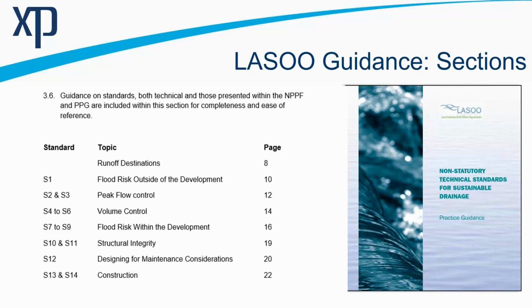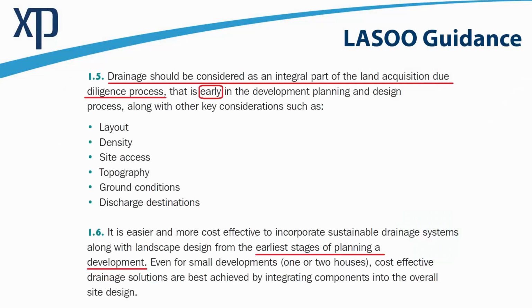With regard to the drainage, the key advice here is that you need to consider this at a really early stage. And when they say early, they mean it's an integral part of the land acquisition process. That's how early, where people need to carry out the due diligence process. So that's even before any planning applications are carried out. It's at the earliest stages when you're starting to plan out a development.